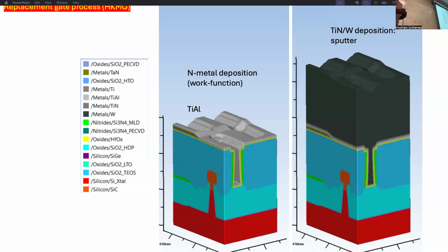We care about the work function to determine the bandgap, right? Yeah. But my question is, now the metal is not touching the semiconductor. No, you're talking about Schottky or ohmic contact. That's different. This is a MOS capacitor. You're creating a capacitor here, but the threshold voltage really depends on the work function difference between this metal and this semiconductor.